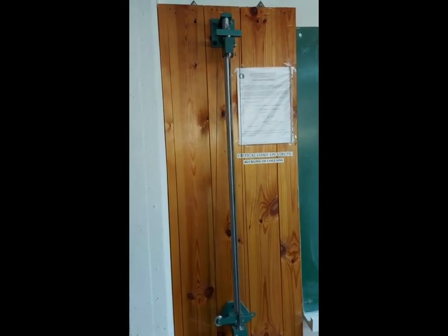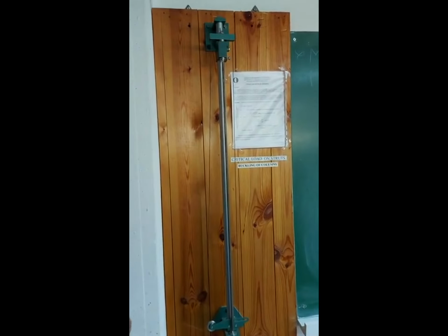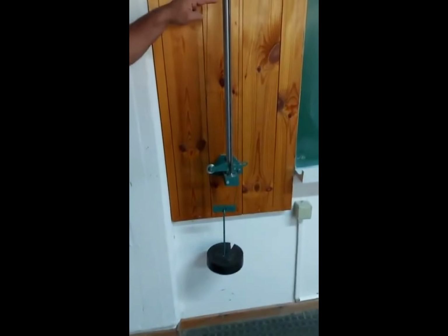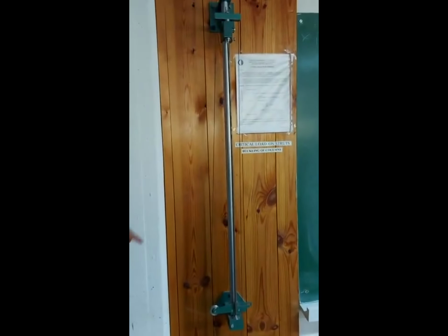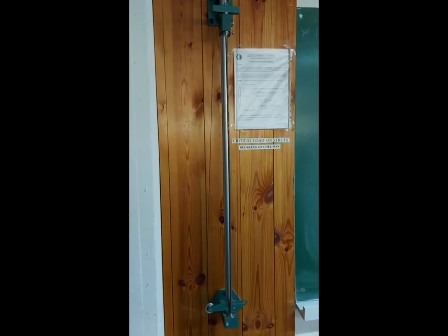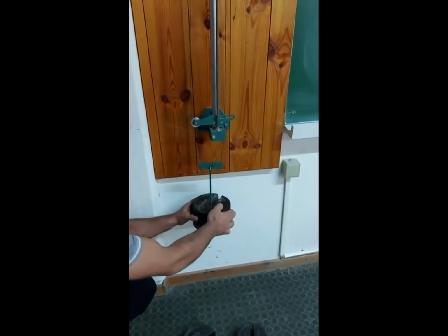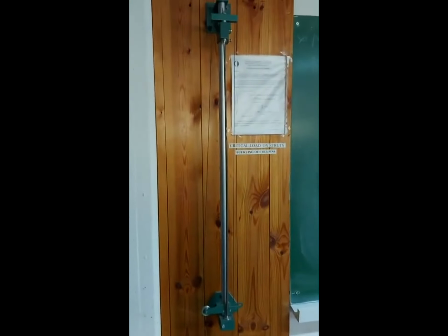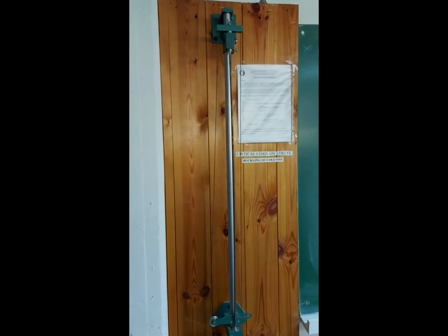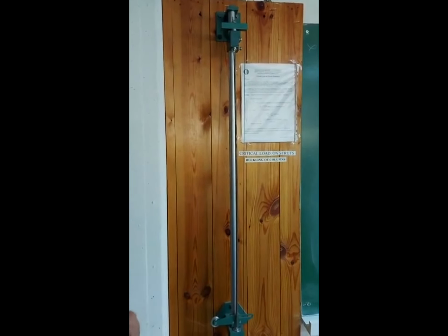If we disturb the rod transversely, it comes back to the original position. As you can see in the demonstration here, when we apply a transverse load, it comes back to the original position. Then we increase the load to 100 Newton by applying another 50 Newton. As you can see, there is no considerable buckling on this rod.